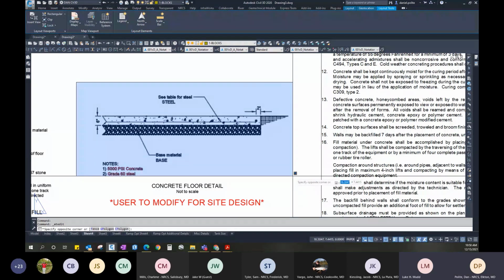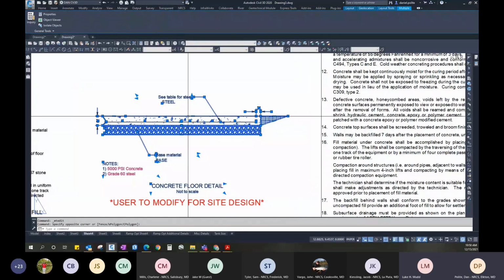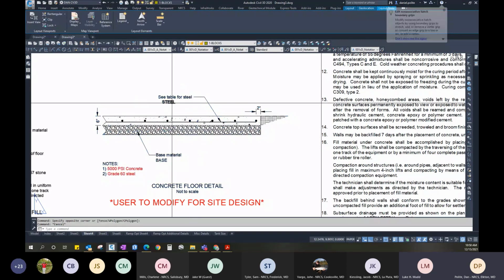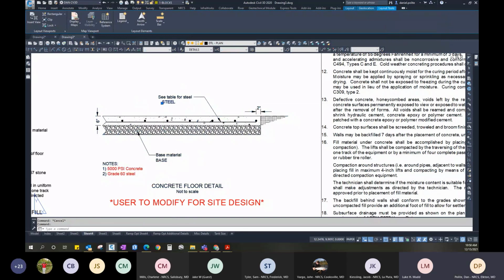Highlight your entire block that you want to create into a block. So I've highlighted everything. Now keep in mind, when you have multiple attributes, in this case we only have 2, which is easy, the order you select those attributes is the order they are prompted to be entered in.